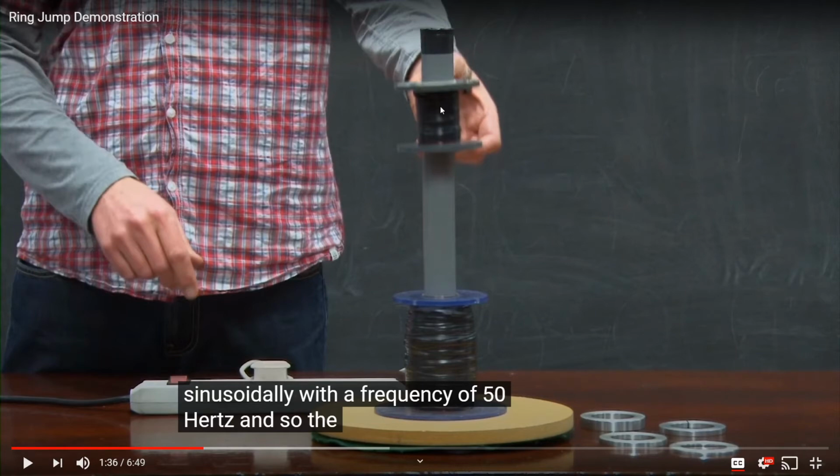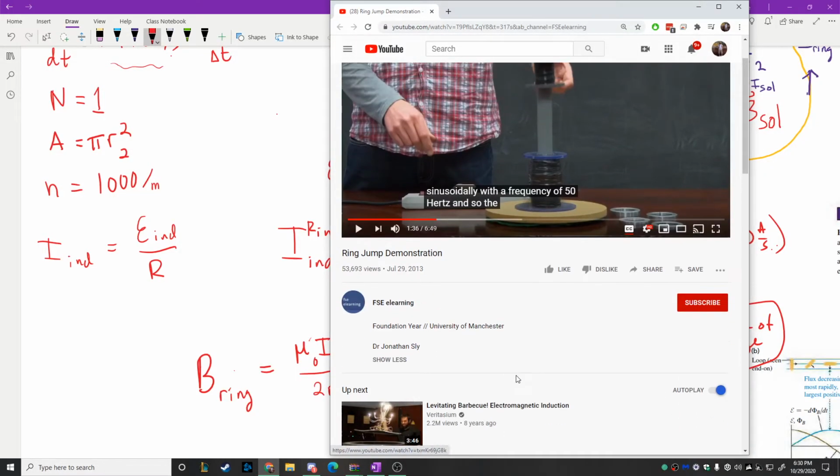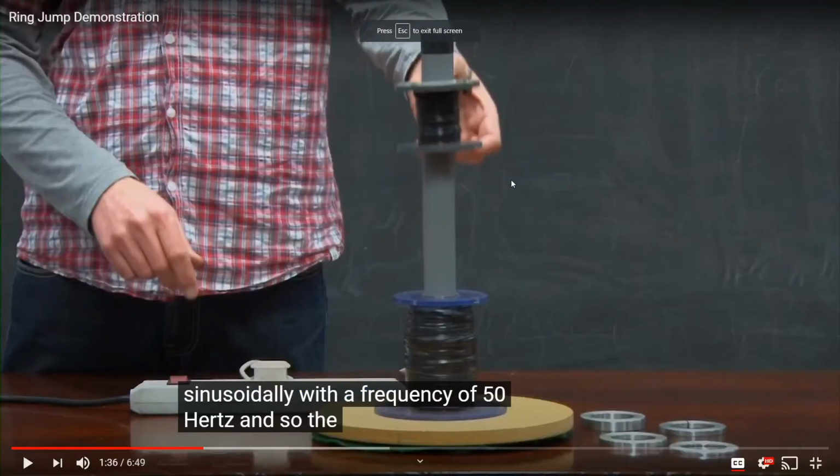So the bar here, by the way, I would assume, although I'd have to look at the details of this, should be some kind of iron core. It doesn't say it. But I know in the one that we do, we use an iron core because that iron core basically enhances the size of the magnetic field by orders of magnitude, due to the magnetic constant for iron being much higher than air.